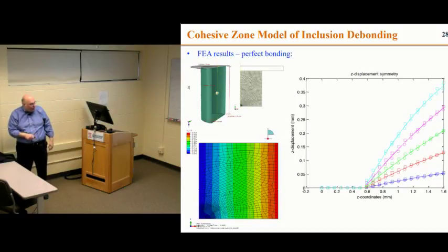And so before they match to begin with, we knew that anyway because we're matching the Goodyear elasticity solution. This also matches the elasticity solution when the thing is not debonding. But what happens when it's debonding? Well, if you assume perfect bonding, and it's maybe hard to see from the back there, but very near the sphere, they do not agree, right? Which is what we expected.